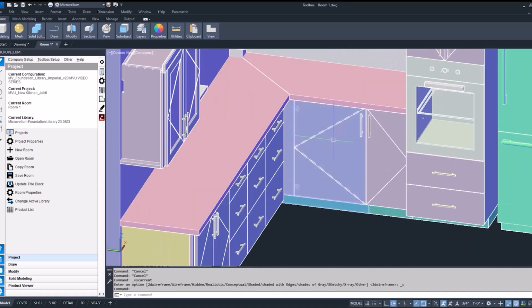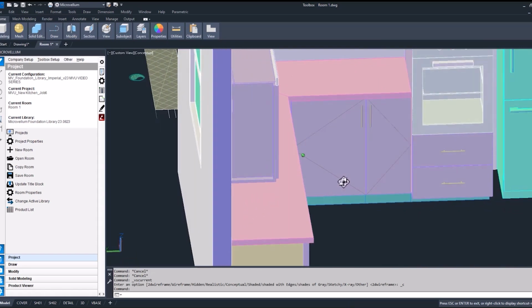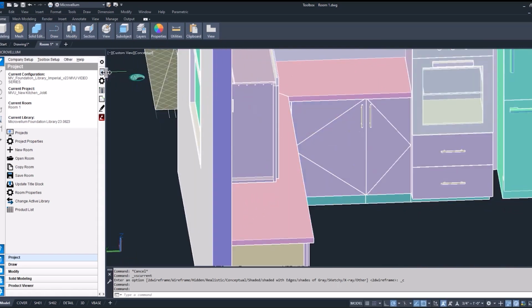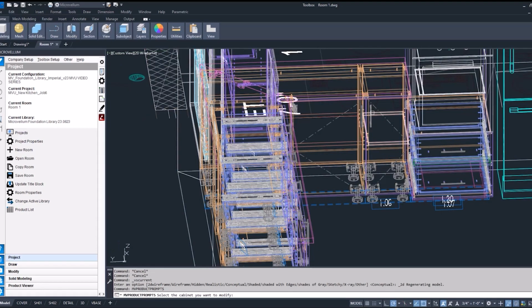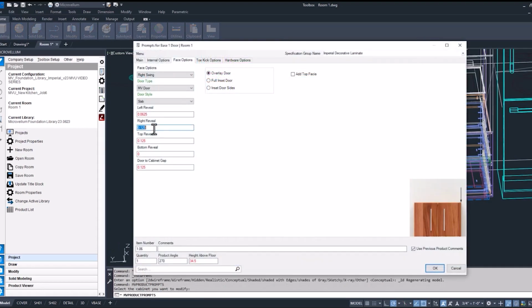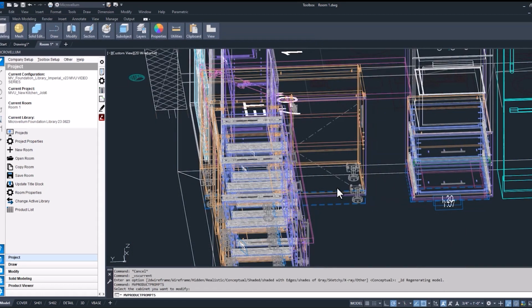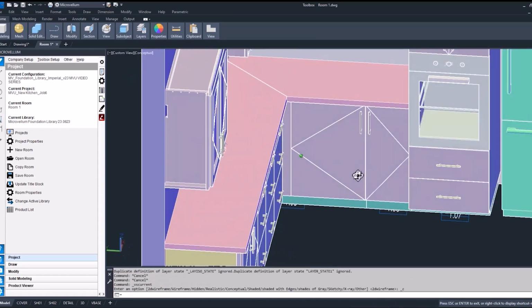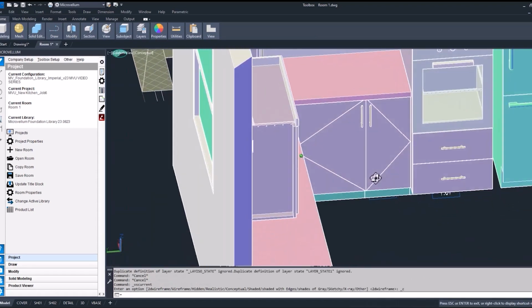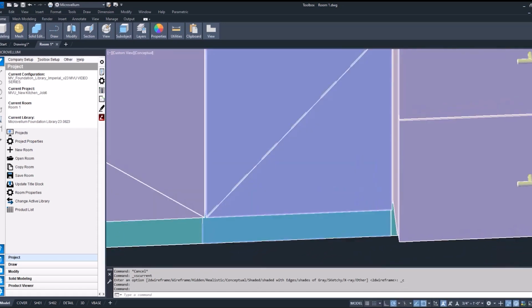Now to the blind corner cabinet, we're going to leave that width alone. If we wanted to, we can make the adjustment, but the only thing I'm going to do next is change the door reveal on the 1 door base cabinet. Now remember, if you want to do that at the project level, it is a global variable, but it's going to change the right reveal on all the products. So that's typically something you're going to want to do at the local level as it's sitting next to this tall cabinet or some kind of end panel.